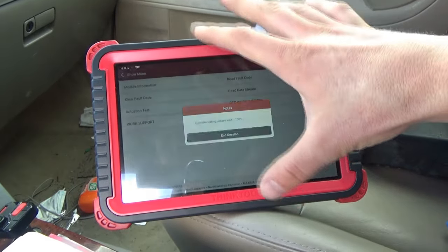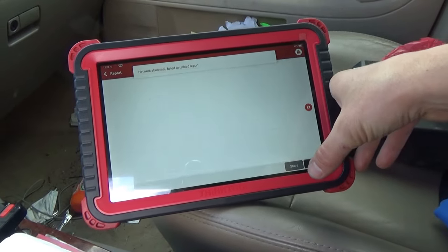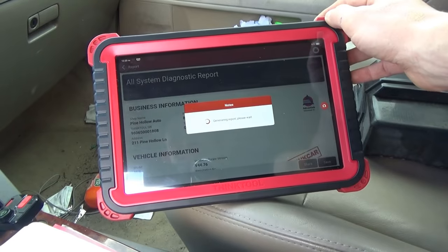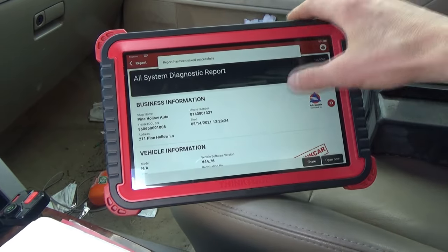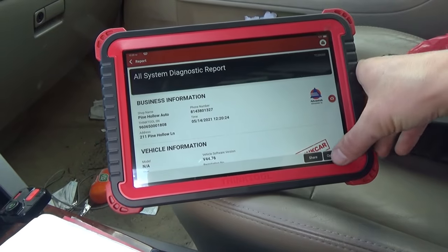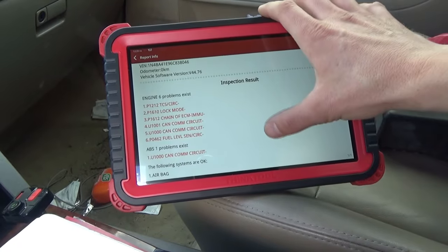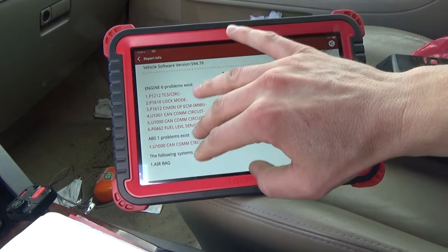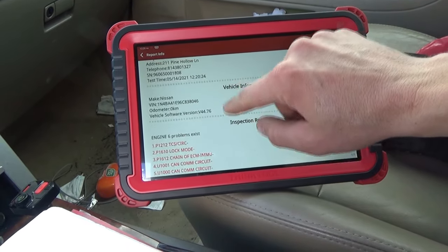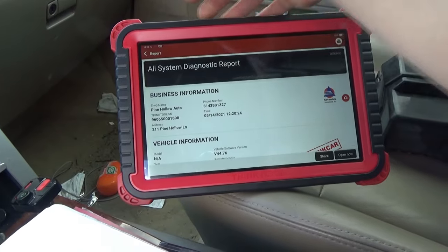What you want to do before starting any diagnostics is save that, pre-repair. Basically keep track of all your codes. So we can only talk to 3 modules on this car. It's interesting. Let's pull up a wiring diagram of this communications circuit.